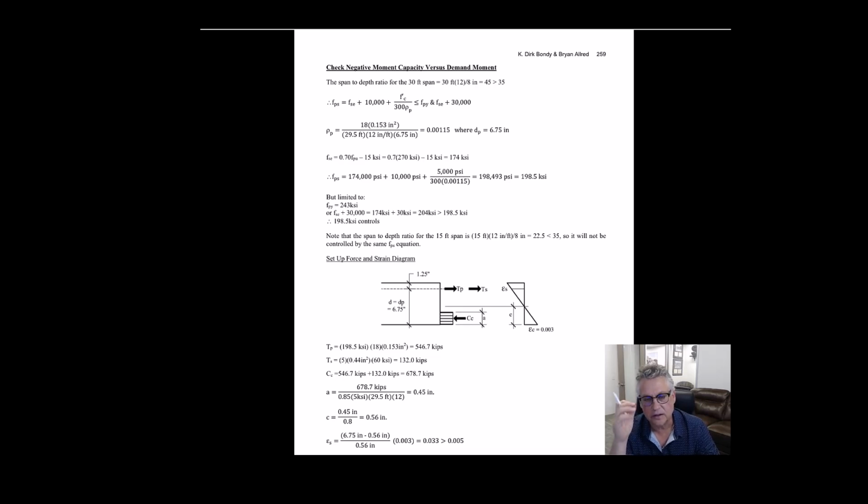And I think you're actually going to see that here. So that's telling you have a good design. It tells you have the right slab thickness for the loading that you have. You've made good decisions if this is the case. If you, on the other hand, are coming up with needing a lot of flexural reinforcement at a lot of locations, and you're well past minimums, probably a good idea to reevaluate the slab, or the one-way slab, the two-way slab, or the beam depth that you have been working with.